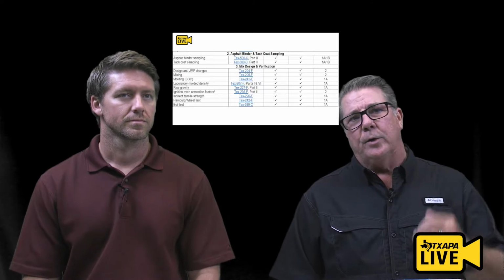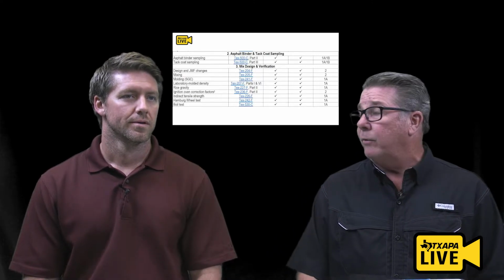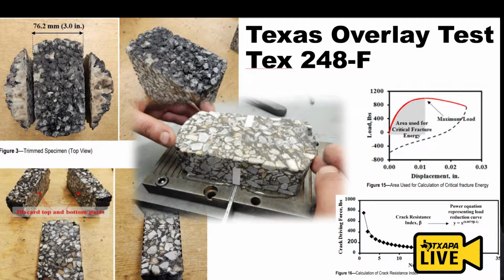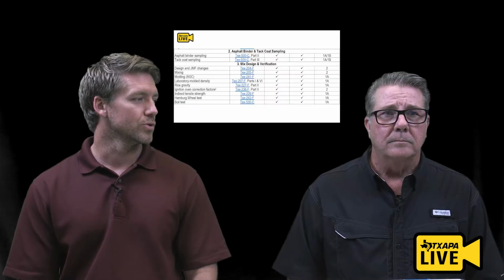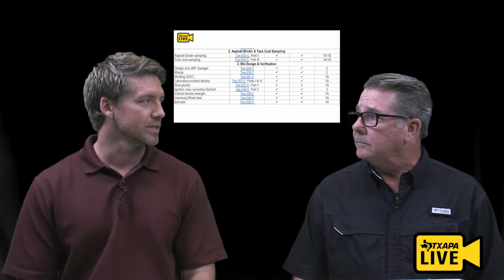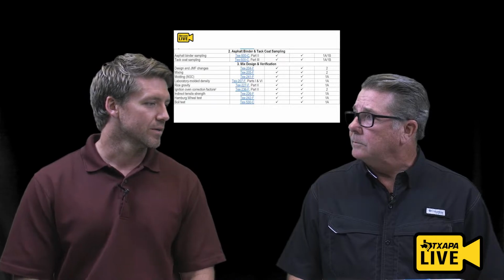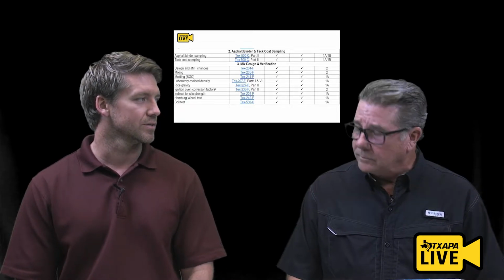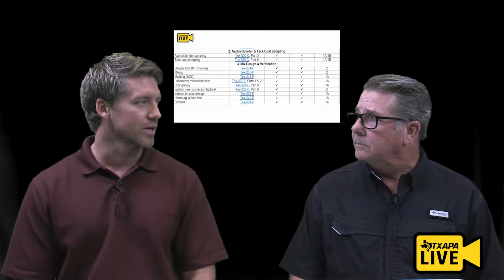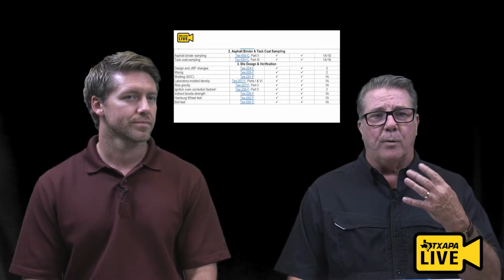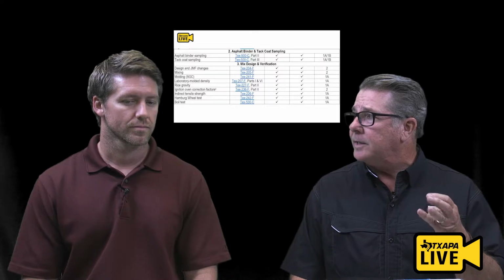So what other test in here that only MTD can run is the overlay test? The overlay test doesn't apply to this example here, but you're right. Currently MTD has 4 overlay machines, and we're the only ones that have a certified overlay machine to run it. I will say that we're currently working on an approved list. Shortly we're hoping to have somewhere around 10 approved machines throughout the state, and we would maintain a sampling proficiency sample similar to our Hamburg system for the overlay, and then we would have approved overlays throughout the state as well.